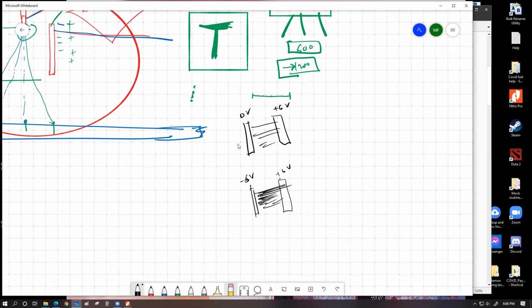Now, try to understand, let's say this is a piece of paper, and maybe you have one cartridge over here. Using that cartridge, you can only cover the vertical drop and movement towards one side, because the ink droplets are negatively charged, right? The ink droplets are negatively charged. So using a neutral plate, you cannot move it to the left. Using a positive plate, you can only move it to the right. Am I correct?